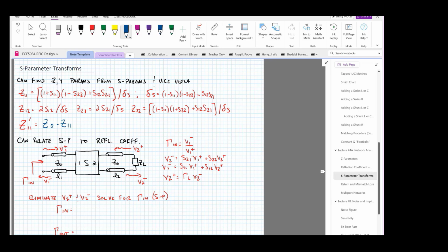So it turned out when they were making coax cables back in the day, around 100 years ago, they could only extrude plastics and whatnot with certain shapes and geometries. They don't have the advanced manufacturing that we have nowadays. And so with the materials and the way that they were able to shape them, they could make a transmission line that had, I think, maximum power transfer at 33 ohms and the minimum loss at 75 ohms.